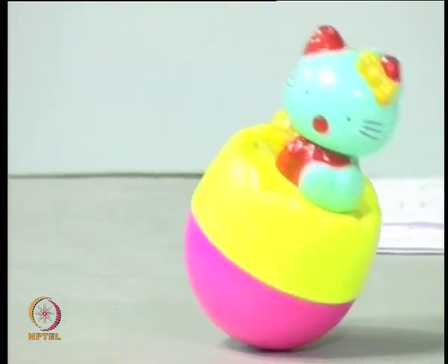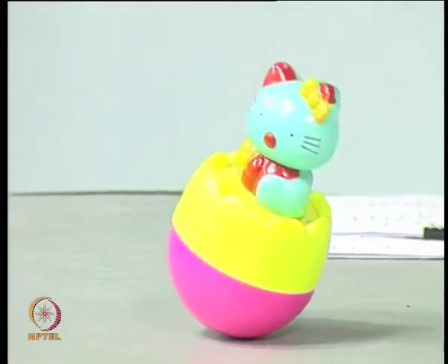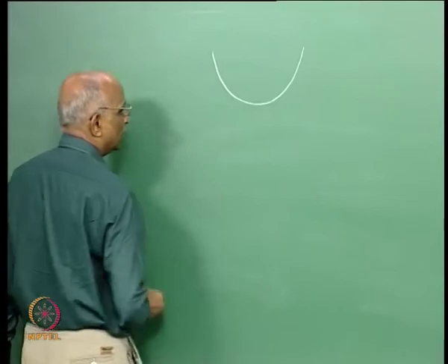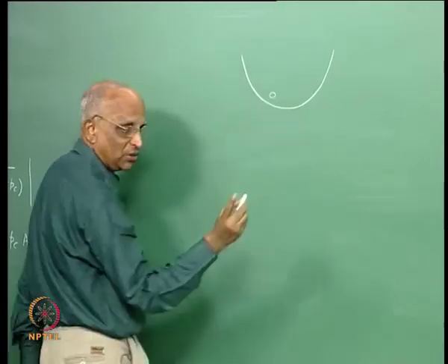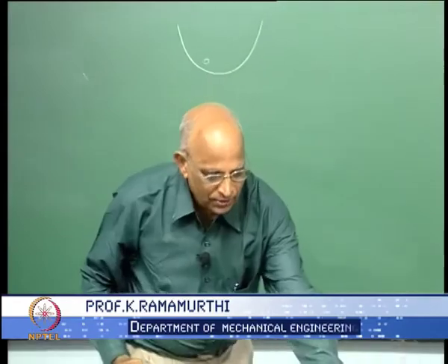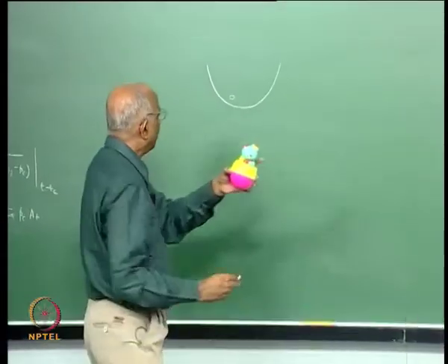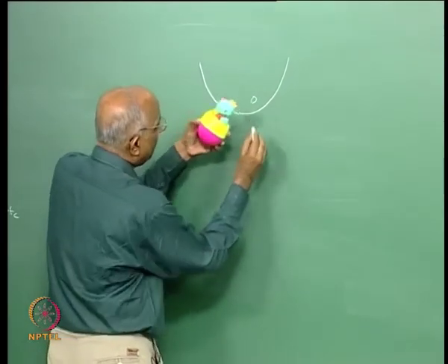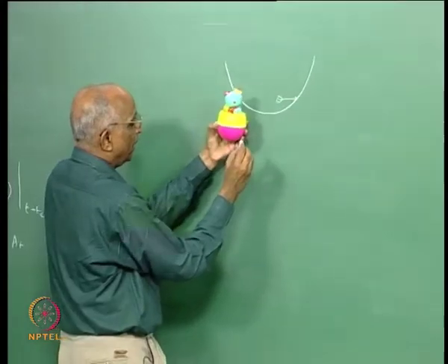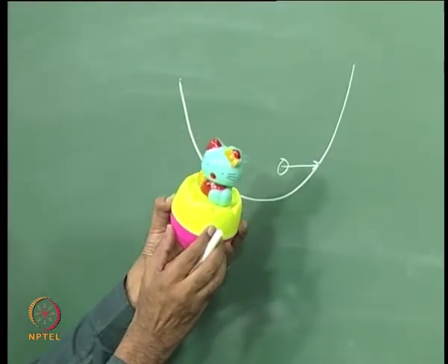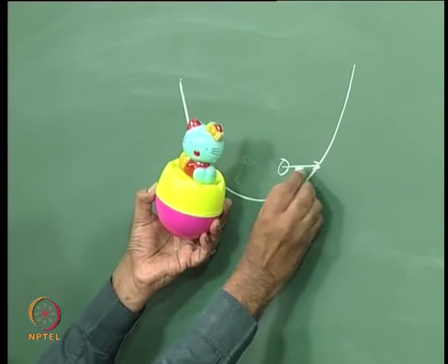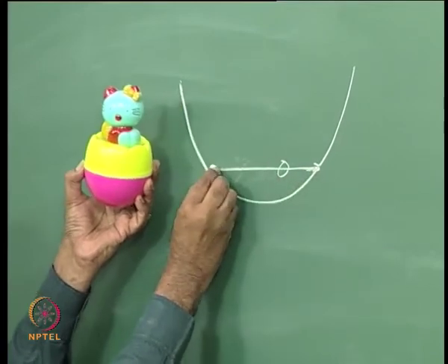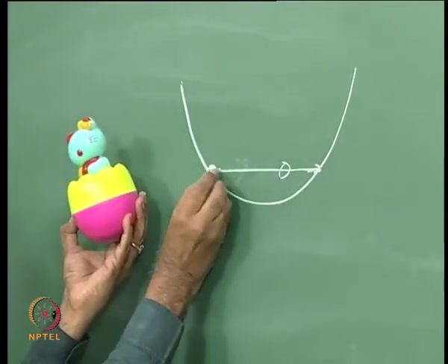It is in a state of neutral oscillations. Why does it have to do this? Let us take a look at the construction of this particular one. Maybe there is a small marble here, which is making this noise. When I shift it, there is a sling and a marble over here. The marble comes and hits over here, much before it has bent over here, and gives a force to this, but when it hits, it rebounds back, and even before it would come here, it rebounds here.